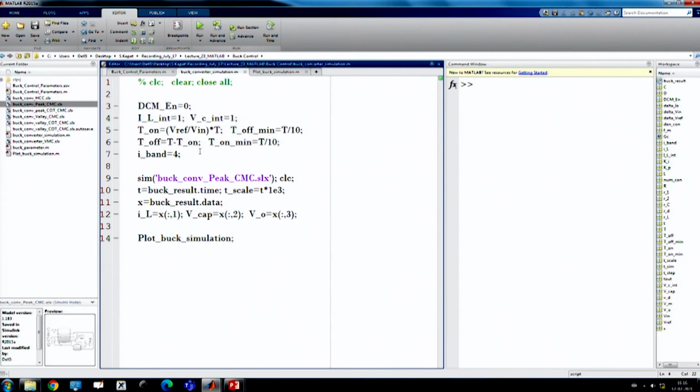Now, as we said in lecture number 19, for low duty ratio operation, since you have a very small on time, you will get hardly any time to continue the comparator operation, and all this we cannot finish within that very small amount of on time when you are talking about a high switching frequency. So, then we talk about the valley current mode control, but valley current mode control for low duty ratio is unstable. So, that we have discussed, we will go for constant on time.